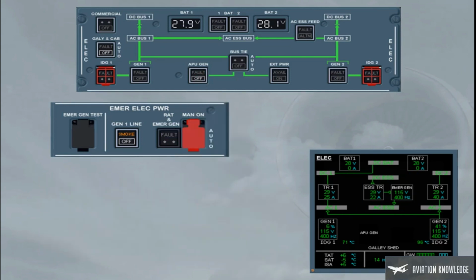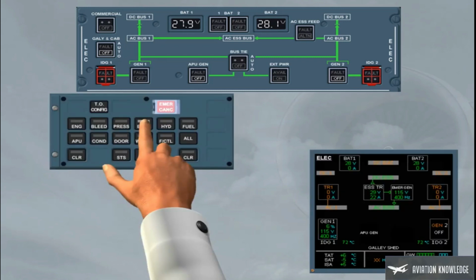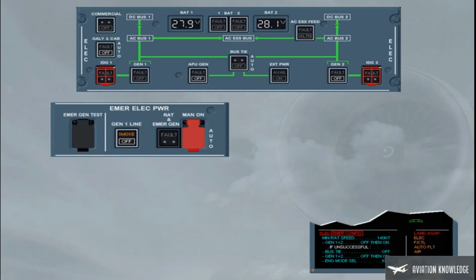As soon as the GEN 2 push-button switch is set to off, the emergency electrical configuration is set, as shown on the engine warning display, and also on the ECAM-ELEC page, when it is maintained displayed on the engine warning display. So, we will stop here, as you should continue to apply the QRH, to know which part of the ECAM has to be followed.